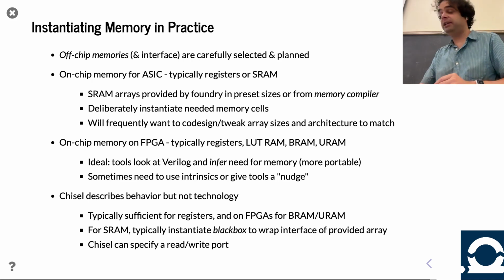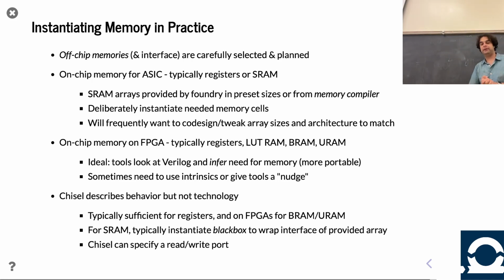If you're a veteran FPGA developer, you might be used to instantiating these manually in Verilog. And if that's something you really want to do in Chisel, you can. You can put those instantiation codes inside what's called a Verilog black box, and it looks like Chisel from the outside, but of course inside you have Verilog that instantiates the thing directly. That works. In the Agile philosophy discourse, I really encourage people to avoid doing that, right?